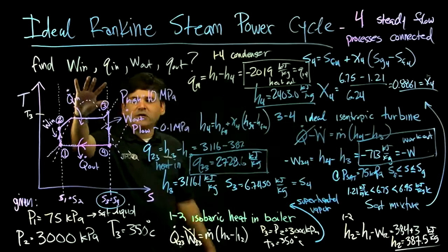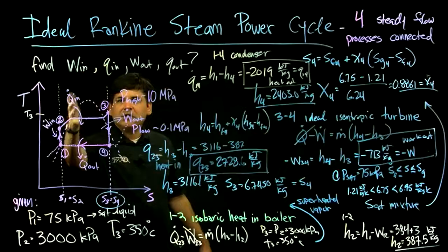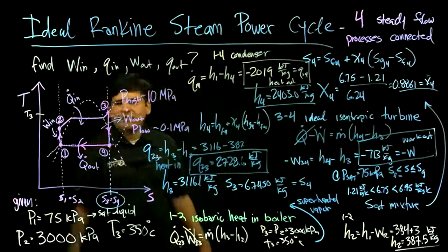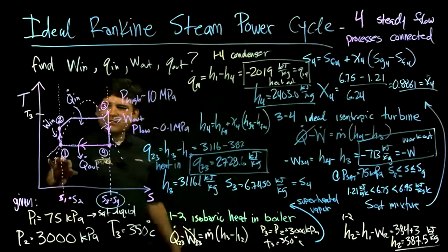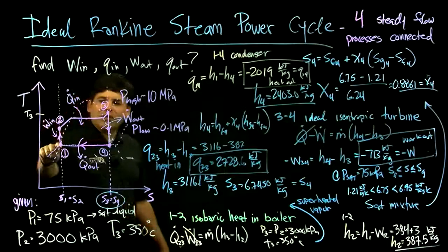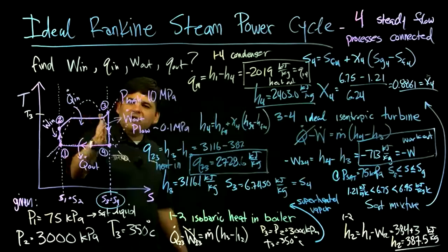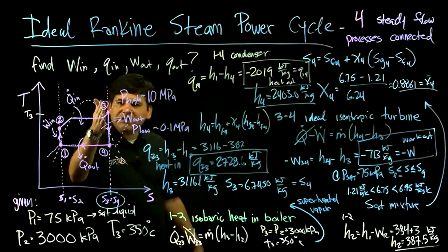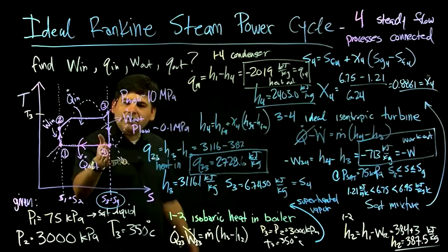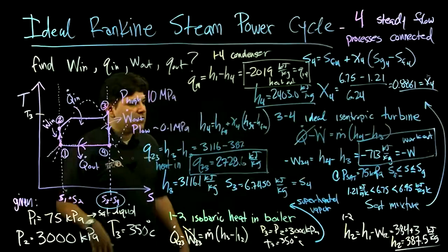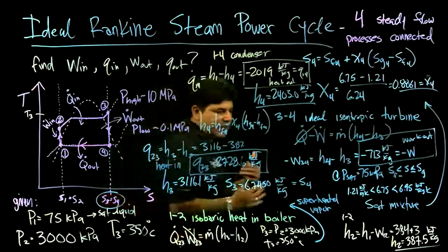That's how a real cycle works. You boil it. It's called a boiler because you boil it to the gas phase. There's always this mechanical work in to go from the low pressure branch to the high pressure branch. And the whole point of this is to get a high enthalpy steam to flow through a turbine and get mechanical work out. So this is a heat engine.